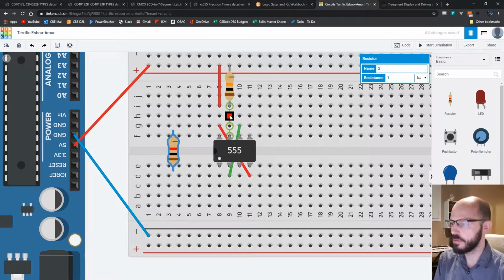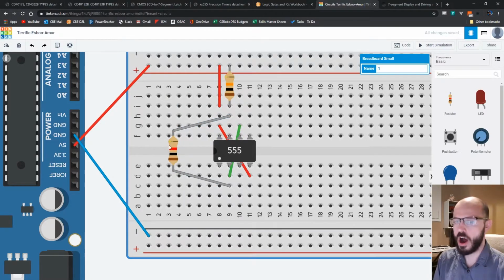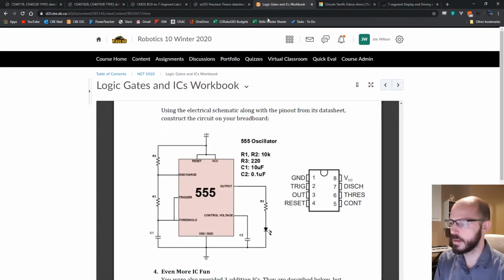And so if I was to go from 7 to 6, that would be a little tight to fit a resistor in there. So I think I'll go from 7 to 2 to make that connection. I'll make these gray so it looks like the legs of the resistor. So I've just got this resistor kind of hopping over the IC, just like my jumpers, and just being careful it's going from 2 to 7, while I have this jumper going from 2 to 6.